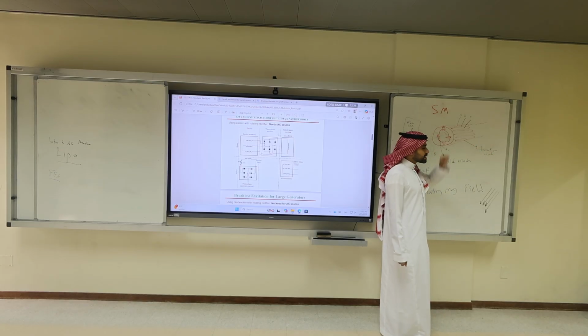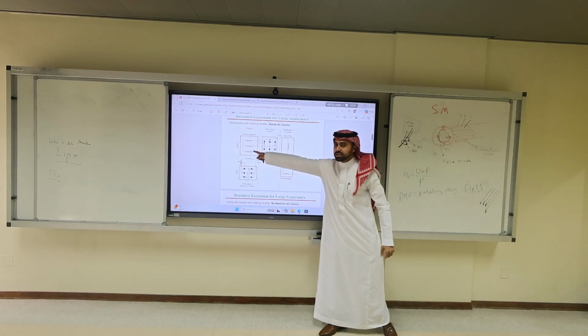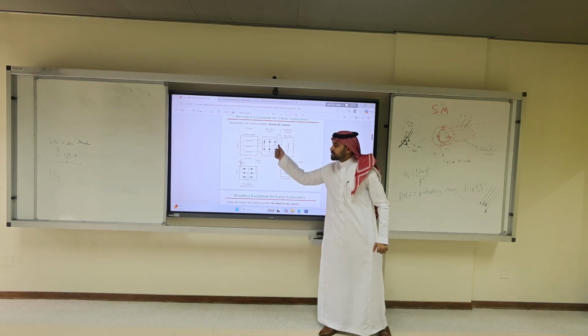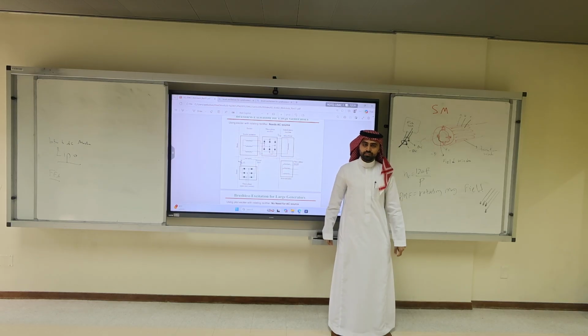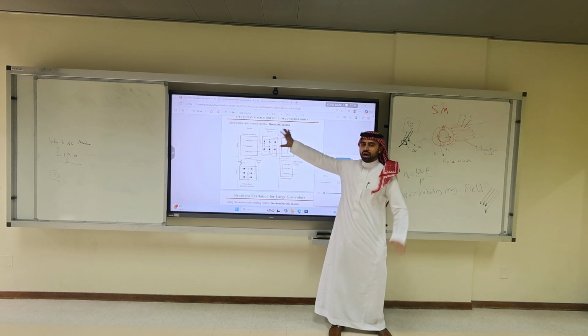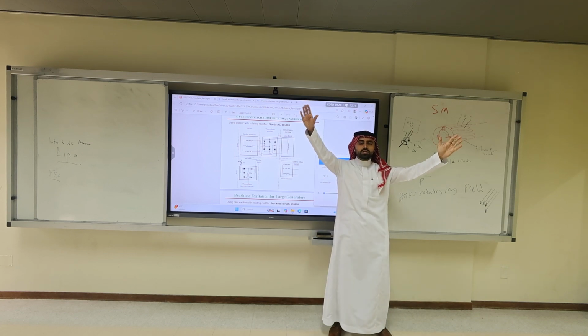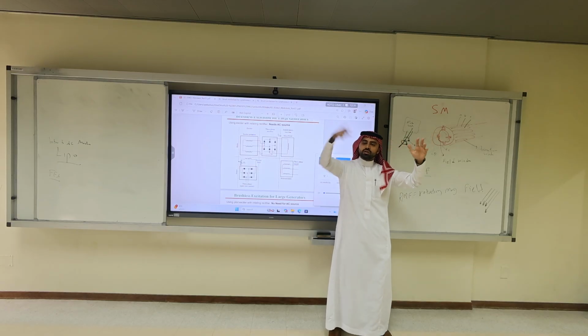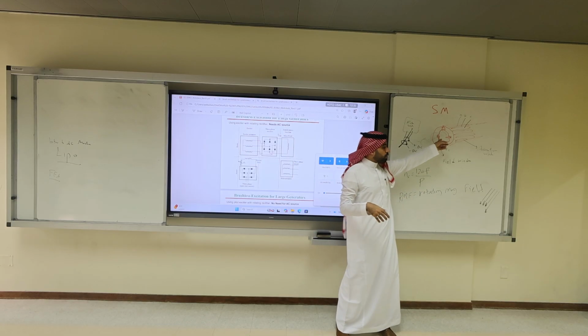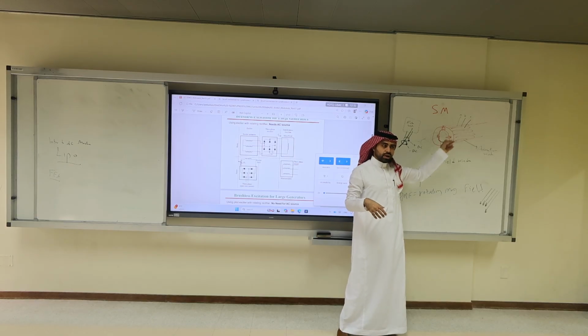Because the rotor cuts the flux lines, it will have an induced three-phase voltage. Apply this induced voltage to another rectifier inside the rotor. You get the DC. This DC is applied to all the other windings. You have 100 windings. You can use maybe 5 for DC, 95 for AC. It's by design. By main windings, do you mean the stator windings? No, rotor windings. Each one has windings, the rotor and the stator.